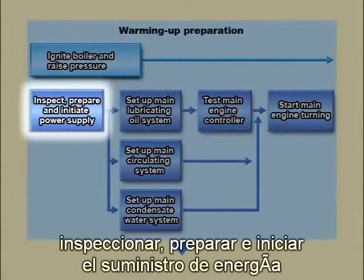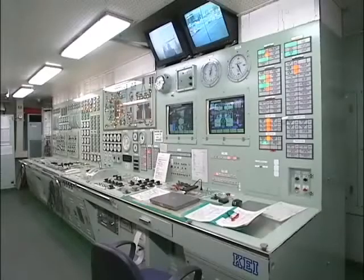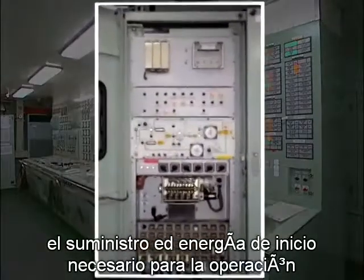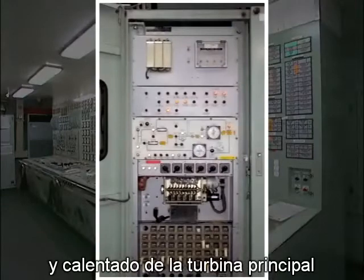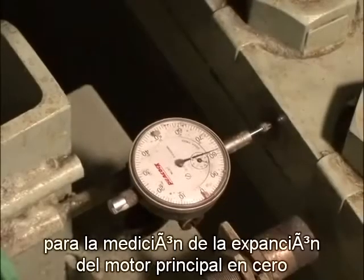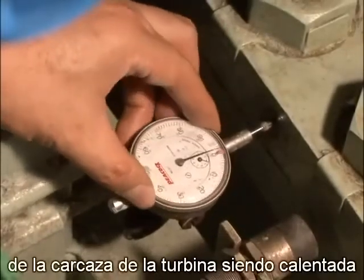Inspect, prepare and initiate power supply. Initiate power supply necessary for operation and warming up of the main engine turbine. Also, set dial gauge for the measurement of main engine expansion at 0 to monitor thermal expansion of the turbine casing being warmed up.